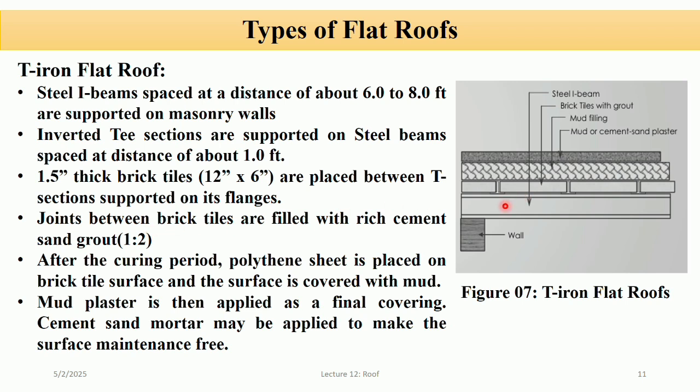After that, after grouting, the surface is allowed to cure for several days to gain strength, and a polythene sheet is placed over the cured brick tile surface to act as a moisture barrier, and a layer of mud is placed over the sheet for insulation. Mud plaster, this is the mud plaster layer, is applied as a final layer, sometimes topped with a cement sand mortar to make the surface maintenance free and durable.